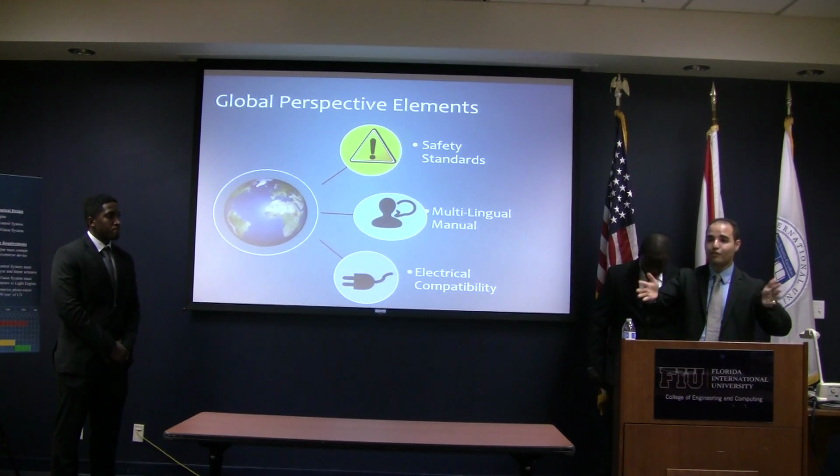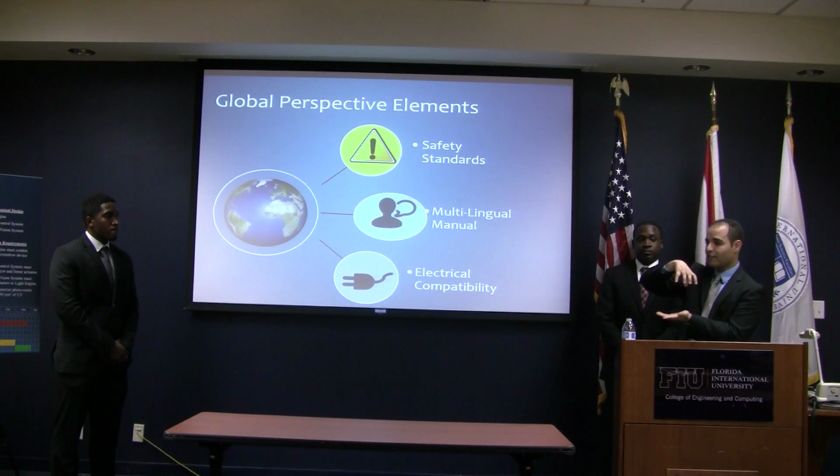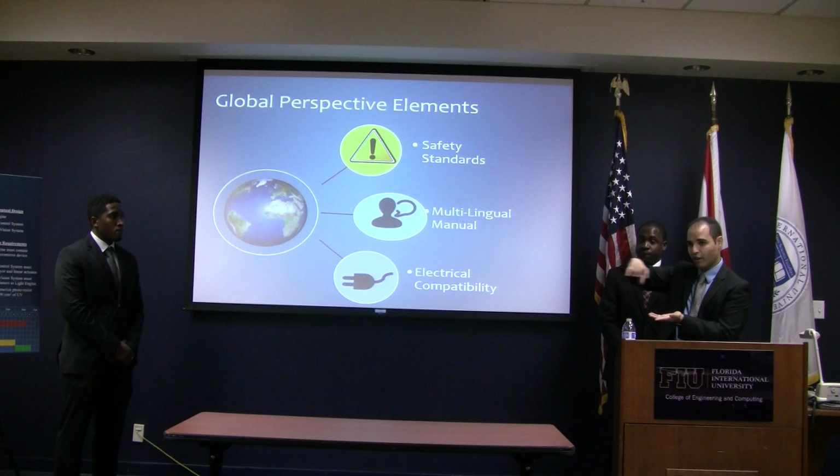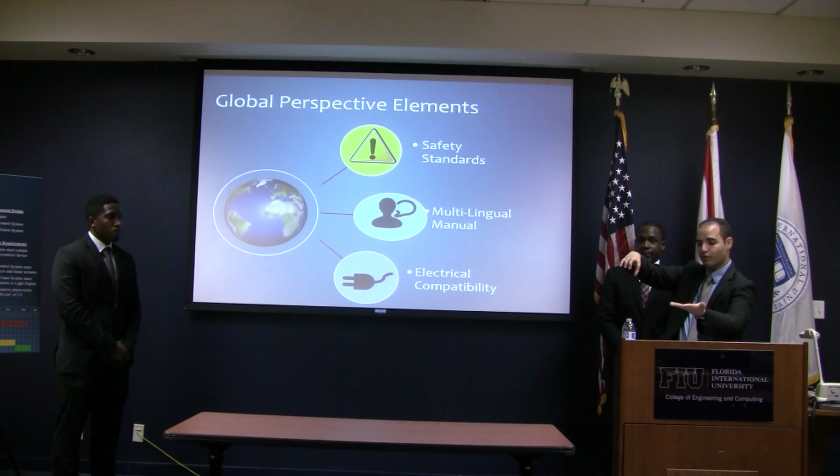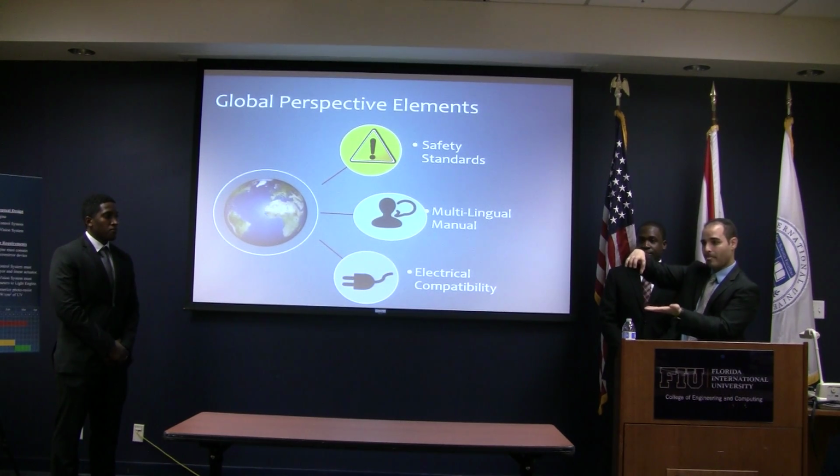So we have an entire screen to expose. How's that going to happen? The light engine is going to be mounted on a horizontal axis and it will scan across. The conveyor belt will move the screen printing frame in the perpendicular axis. So we're going to have